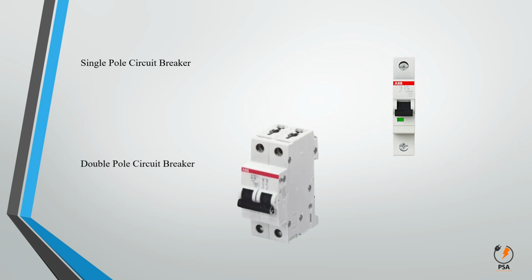Double-pole circuit breaker. In control panels, double-pole breakers look like double throw switches. They can also be used to power appliances with low-voltage circuits, central air conditioners, clothes dryers, water heaters, baseboard heaters, and even hot tubs. Double-pole breakers consist of two hot wires connected to a neutral wire. With this design, a short circuit in the wires of any of the two poles causes both to trip. They are typically used for a single 240V circuit, but can also be used for two separate 120V circuits.